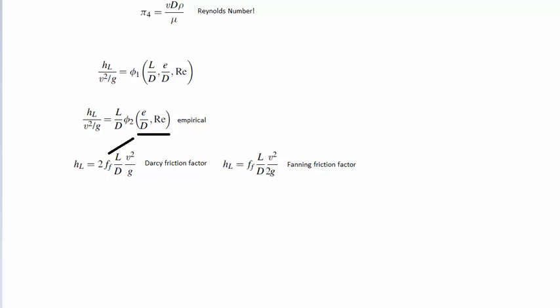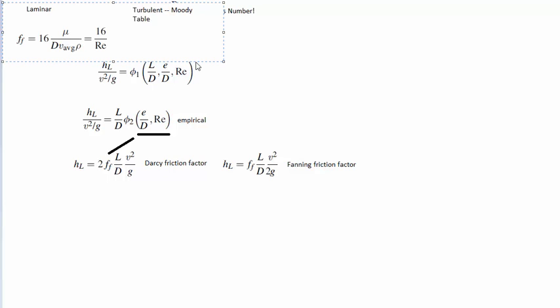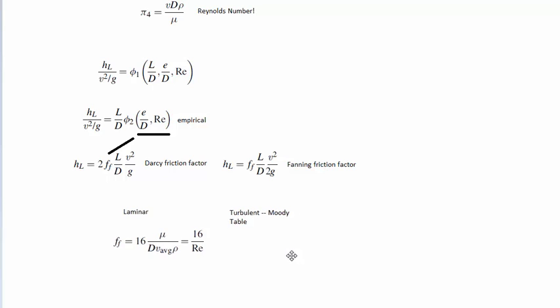It's just kind of hanging out there. Okay, so what about this Fanning friction factor? So we know that it depends on the Reynolds number, and we know it depends on the roughness of the pipe. The problem there is that they started characterizing this Fanning friction factor, and the problem is it really depended on the regime of the flow going through the system.